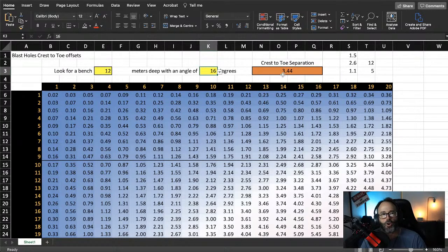So we're going to have to overburden the second row if we want to maintain that row to 5, or we would increase the angle and say, well, we can't do a 5-degree and ensure our toe. We might have to do a 10-degree and ensure our toe. These are all decisions you make in the field. The next row of holes would have a little wobble in it.